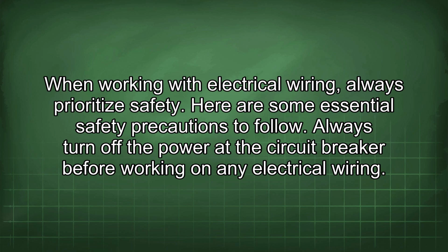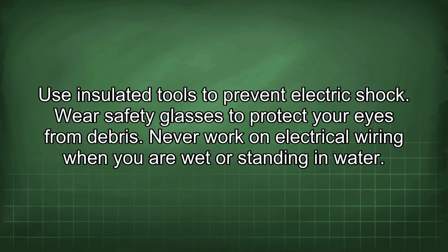Always turn off the power at the circuit breaker before working on any electrical wiring. Use insulated tools to prevent electric shock. Wear safety glasses to protect your eyes from debris. Never work on electrical wiring when you are wet or standing in water.